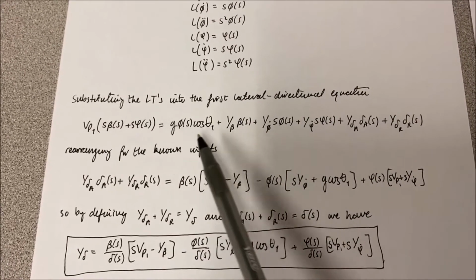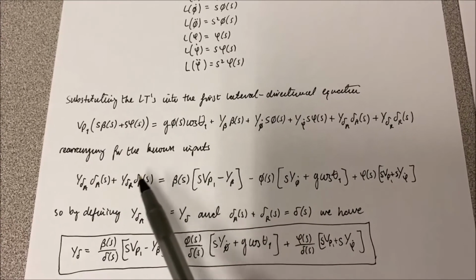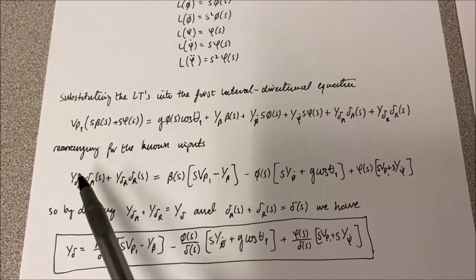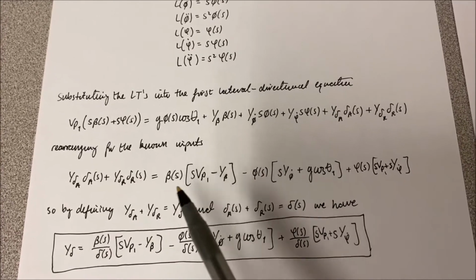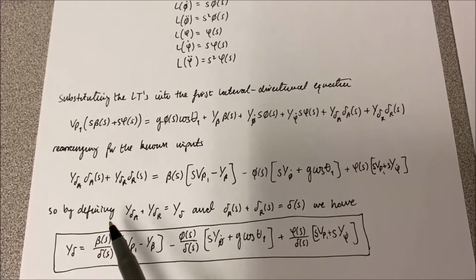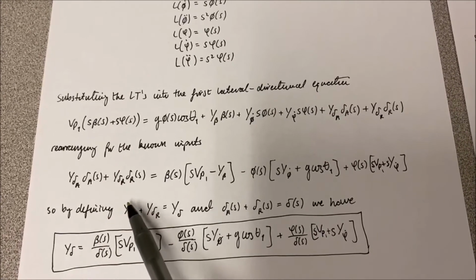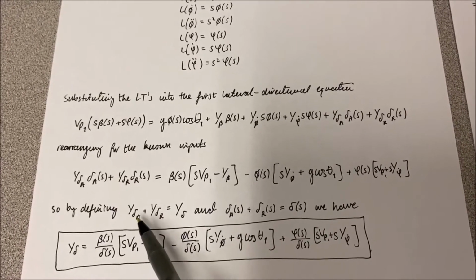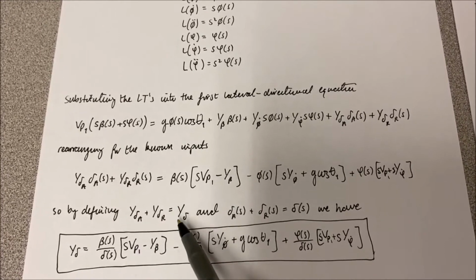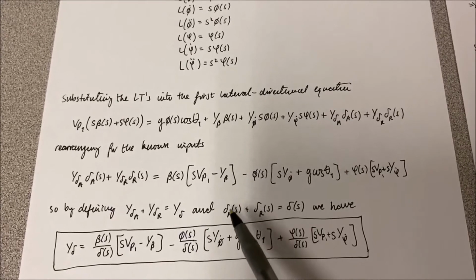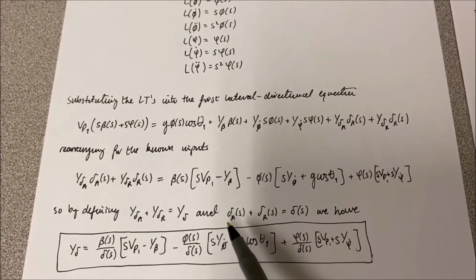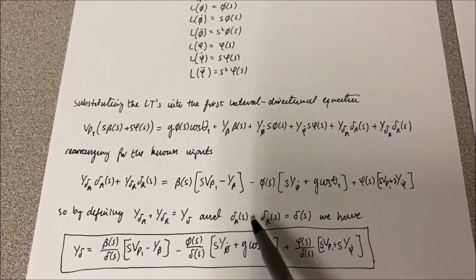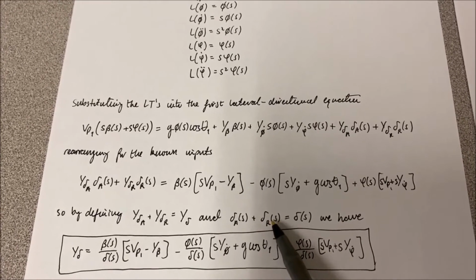So here we've written out the first of those equations with the Laplace transforms in it. We've rearranged them for our known inputs. So again, our known inputs this time are going to be the deflection angles of the ailerons and the rudder. And basically we're just going to combine those into one function. So we define the y of delta A and y of delta R, so side force coefficients with respect to the aileron and rudder deflection angles. We're just going to call that y delta, and we're just going to combine these two functions of a complex variable so that the deflection angle function of the ailerons and the deflection angle of the rudder functions as just delta S.